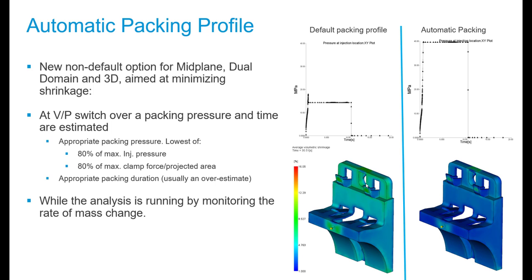Default is still our old 10 seconds, 80% of maximum injection pressure, but we know for a fact that this default packing pressure is in many cases too long or too short to have an accurate representation of reality. But in many cases, the user will not have an idea what is going to be appropriate in reality.